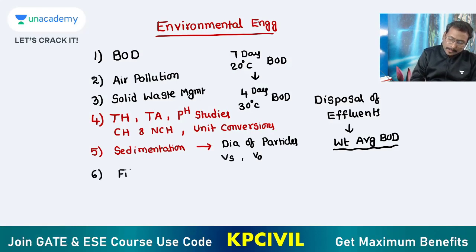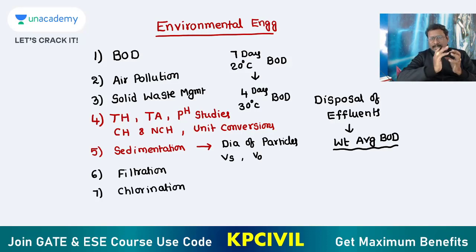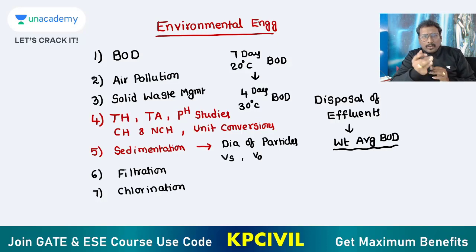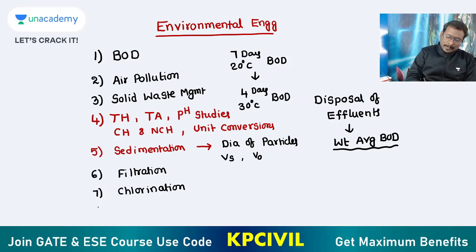Then filtration, chlorination. Especially in filtration you can focus on filter hydraulics, filter design, water quantity, wasted percentage of water for backwashing, and in chlorination, the amount of bleaching powder required, those are important.